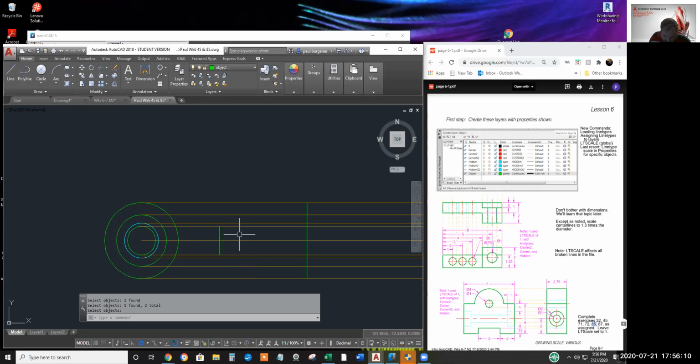I think the textbooks would have put as many dimensions on in a single view. The 44 could have been put on the top view. It looks like that 12 unit could have been, well, dimensioning the hidden lines is, either way it's a hidden line. So yeah, the 44 and the 12 in the right side could have been put in the top view.